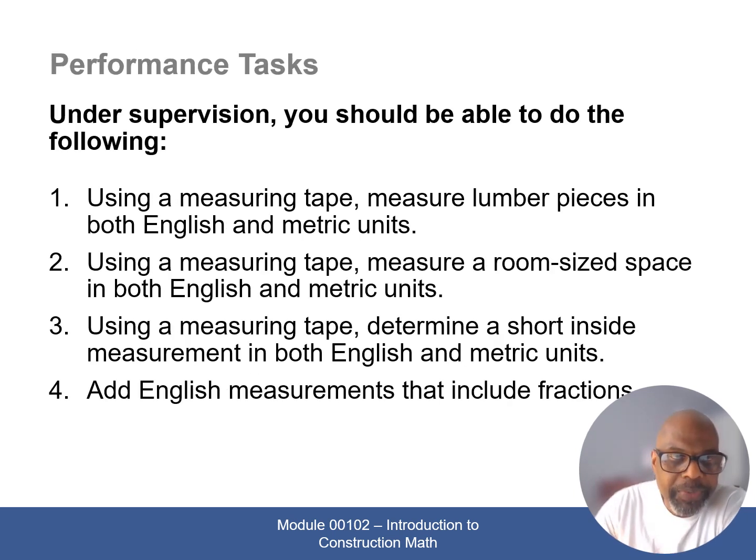There's a performance test, and we'll try to get that done next week using a measuring tape to measure lumber pieces. I will have multiple pieces that you have to measure accurately. I already know what the length of them will be. For this test you would have to verify, make sure your numbers come up to what I have. Also, you should be able to use a measuring tape measuring a room size space in both English and metric units, using a measuring tape to determine the short side of measuring in both English and metric units. And lastly, you should be able to add English measurements that include fractions.